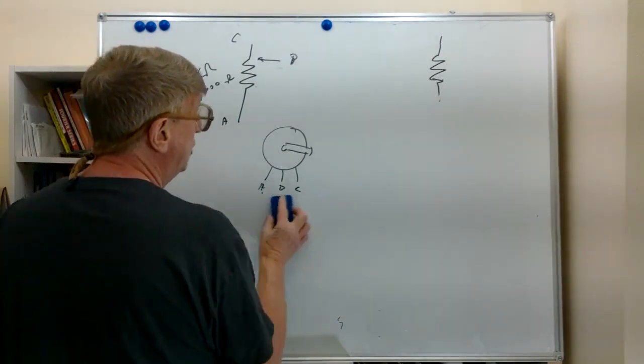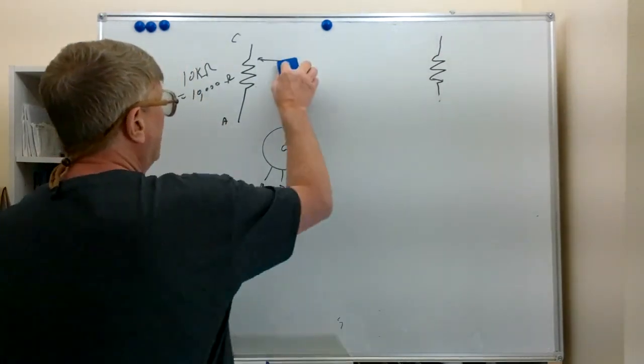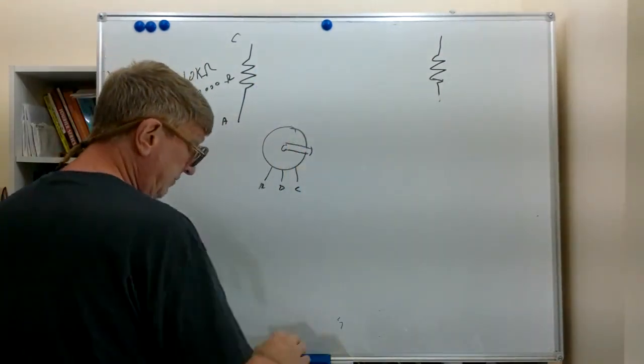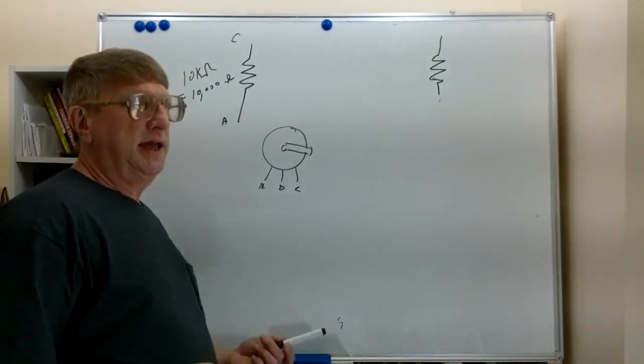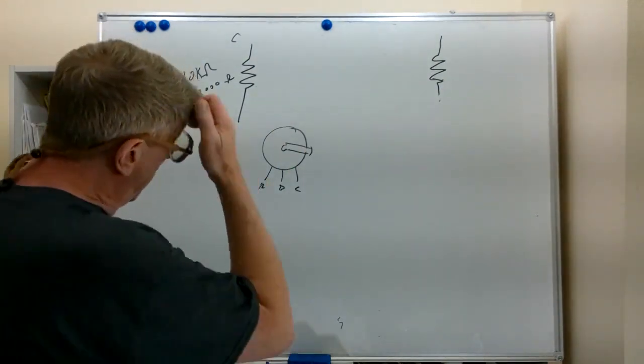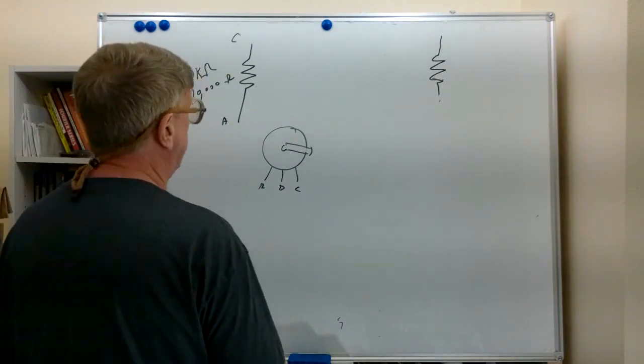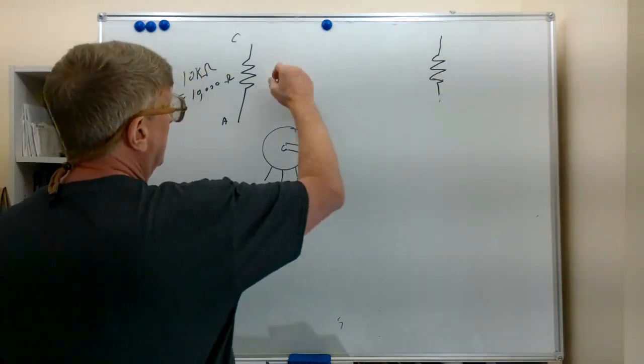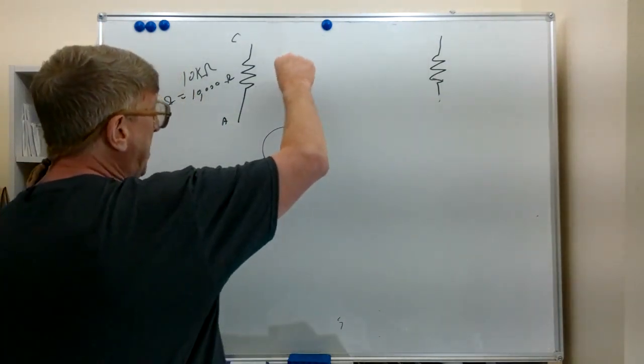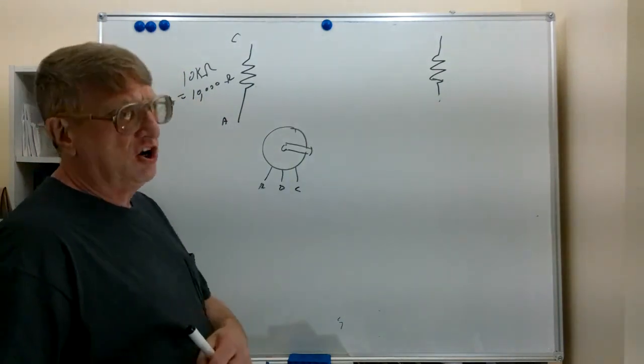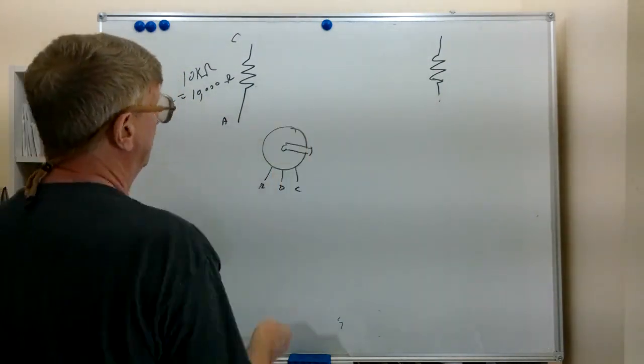We also have resistors with different taper. An example is what we call audio taper. What happens on the audio taper is that change at the bottom represents a far lesser change in resistance.